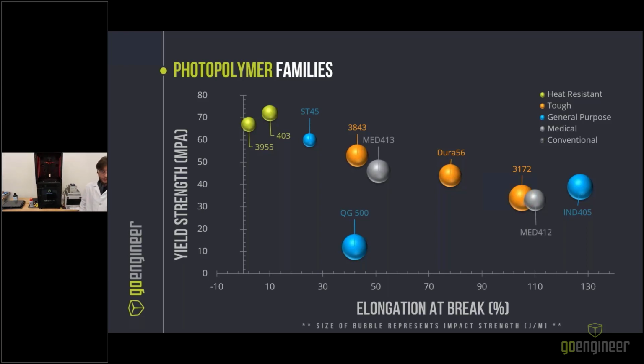The medical resins are specifically formulated to be put into a medical type environment. This is not to say that you can only use a Med 413 or a Med 412, but these materials were designed and will work much, much better in a medical environment than ST45, for instance. ST45 can be sterilized. It does have a cytotoxicity rating, but that was not the original intention of developing that material.